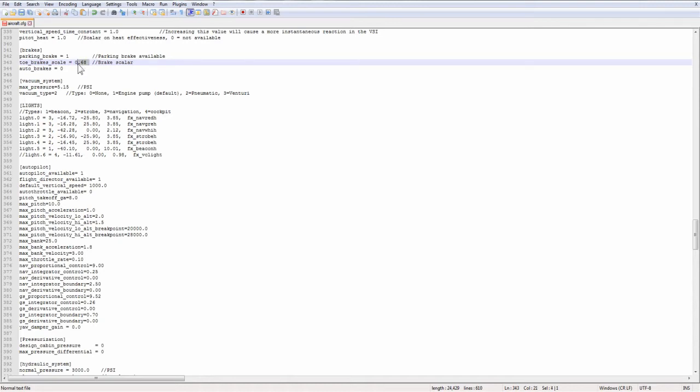However, be aware that if you're using a trigger on a joystick, for some reason the sim will apply the brakes instantly to full with a trigger on a joystick. However, if you're using the keyboard commands, they actually don't instantly go to full. They slowly go up to full with the keyboard commands. So this defines the effectiveness of the brake at full braking. So tapping your keyboard will actually not let the brakes get up to full, and you can sort of ease on the brakes like you would in real life. Whereas using your trigger is like full braking instantly. So be aware of that.